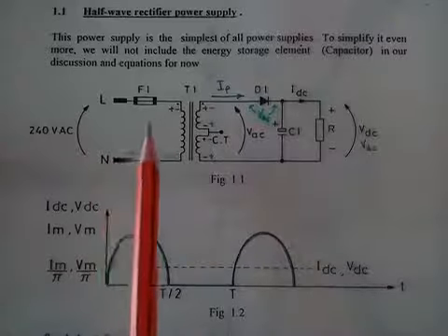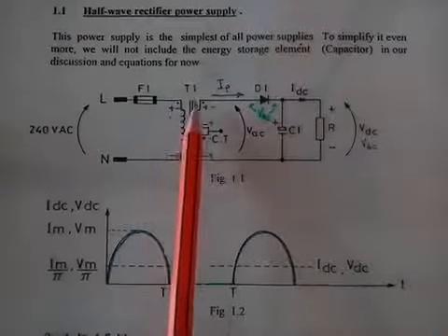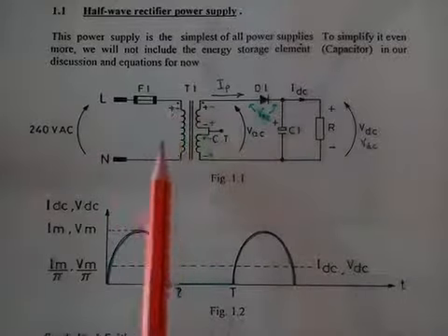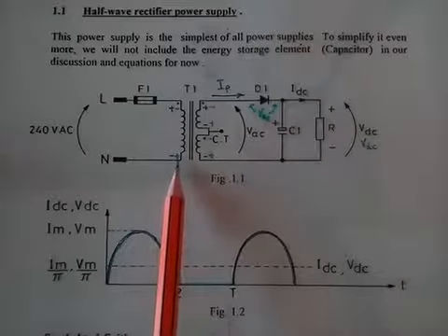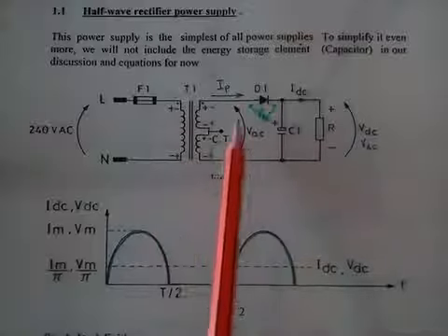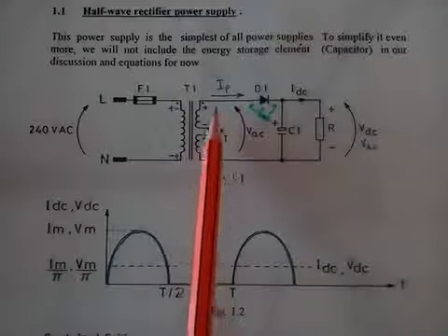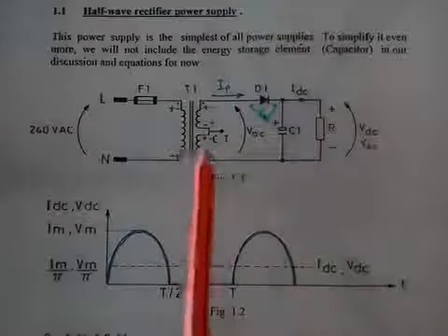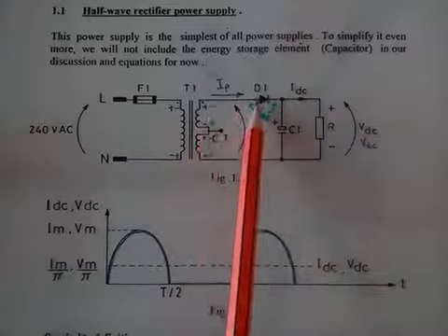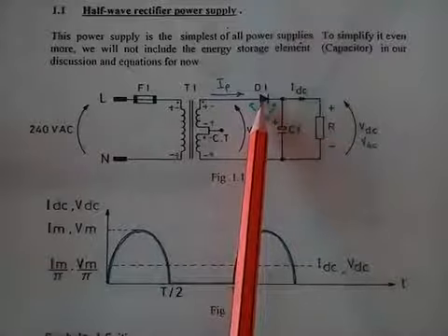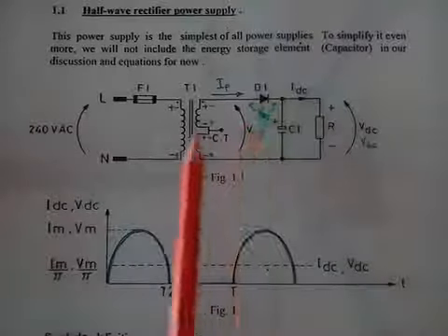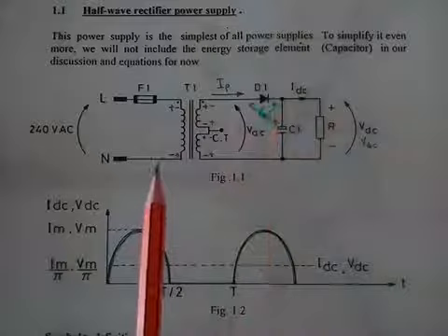Okay, so this is the half of the sine wave that will be present across the load. Now, when the polarity is reversed, where you have your negative in here, that's green polarities, you have a negative in here, and you have your positive in here. The same thing happens in the secondary. You have your negative in here and your positive in here, and the negative in the cathode, and the anode, means this diode will not be forward biased and it will not conduct.